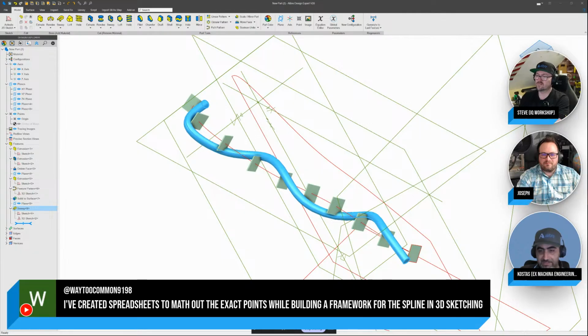That was handled by Excel. So once you get that deep in it, you can do some amazing stuff. And the beauty of it is you can just then import the CSV file with the points into Alibre and get your trajectory. So that'd be another way to do it if you wanted absolute precision.